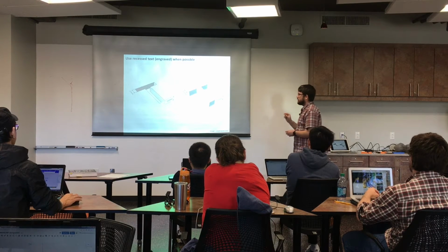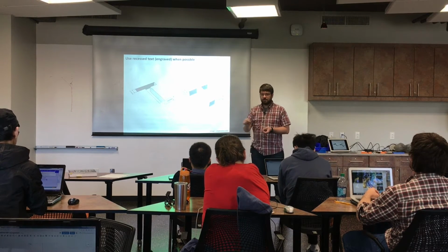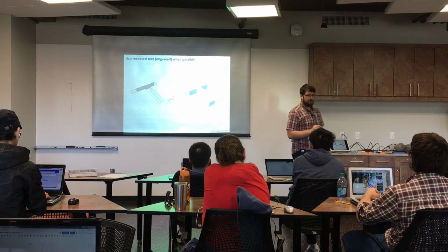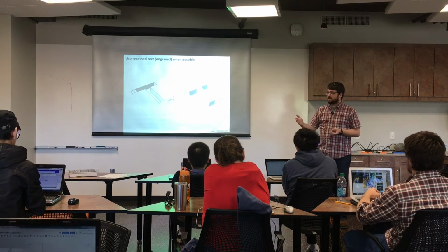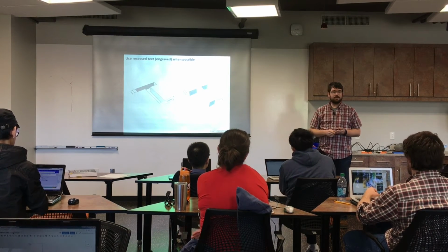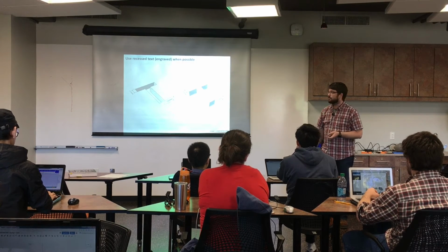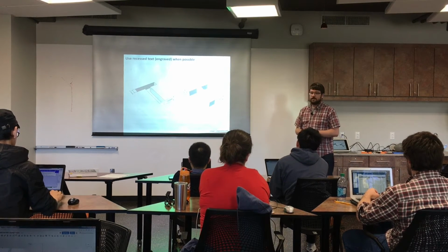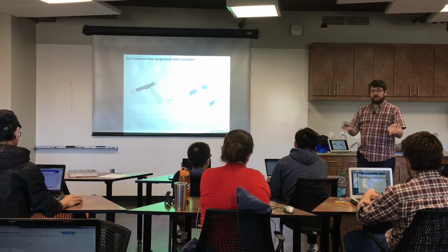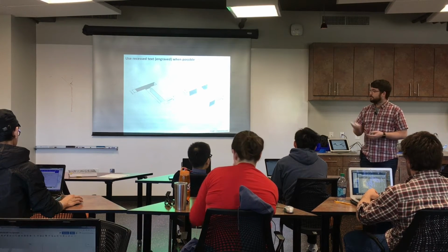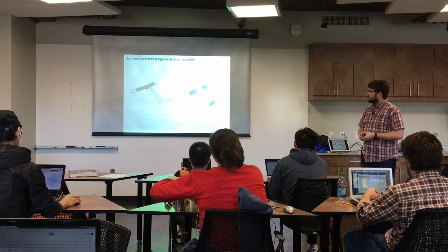Embossed lettering that's really small will probably result in the printer dragging filament all over the top of your part, maybe a failed print, and it also is something that can get caught on and sheared off pretty easily because such thin lines aren't very strong. So go with engraved lettering on your part if you need lettering. It is a nice way, if you're designing a front panel for something, to dress it up a little.